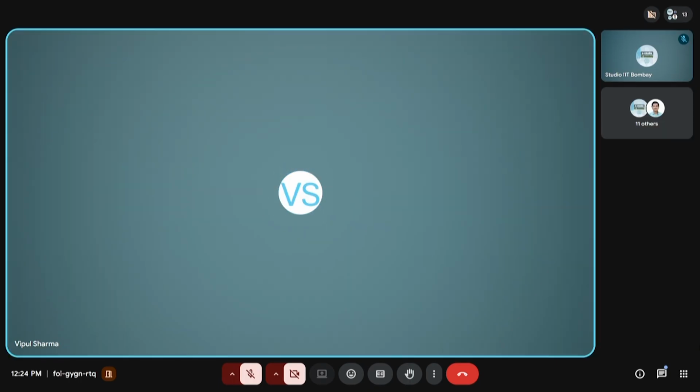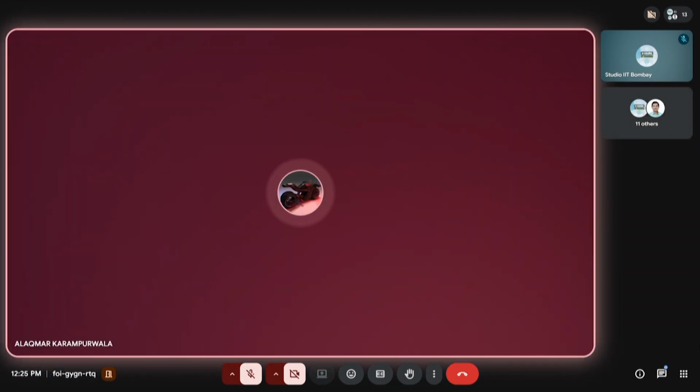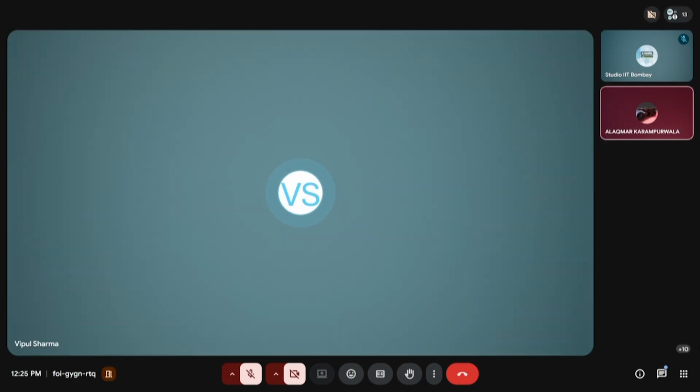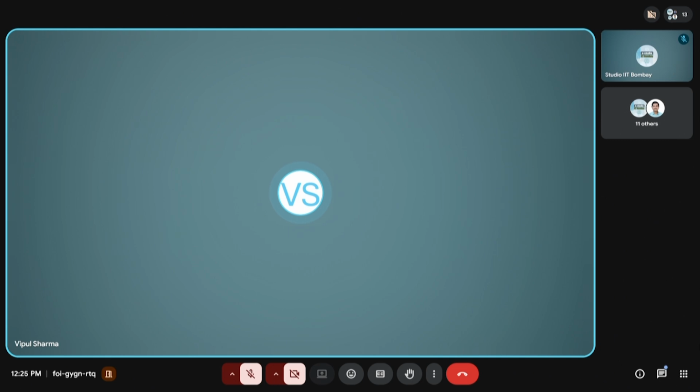So any other queries, everyone? Sir, I'm not able to move the pins. Whenever I press I to select that instance, it shows me the top cell window selected, and I cannot move any of the pins. If you are seeing a top cell window, press the semicolon key on your keyboard. Sometimes, while building a box, Magic selects everything and takes you to the top cell of the hierarchy in your layout. If you want to break that hierarchy, press the semicolon key, and then you can choose the individual components in your layout.